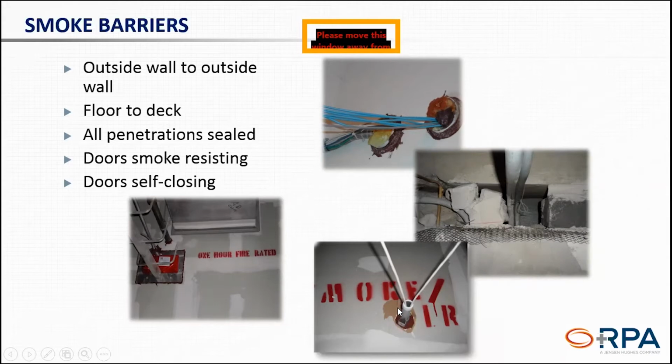You'll see that if you use any of the different fire stop manufacturers. If you look at their systems, you'll see protection both at the wall and where the cables come out of the sleeve or pipe. Or we just have missing block altogether. Want to make sure that those walls are intact from deck to deck, and that's an example of that.